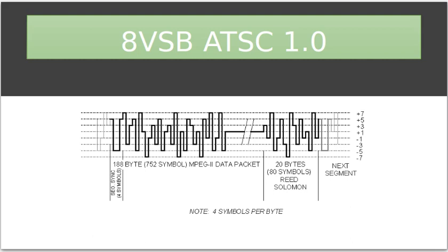Then they simply multiply it up to a carrier. Now if they simply transmitted that, it would occupy 12 megahertz of bandwidth. But the FCC said it has to occupy 6. So what they did is they filter off one of the sidebands, and also throw in a pilot carrier to help the receiver coherently demodulate the signal. But as you can see, yes, it's a digital modulation, but it is still essentially an amplitude modulation. You can think of this step signal here as the voice, and we're simply modulating that up to a carrier.